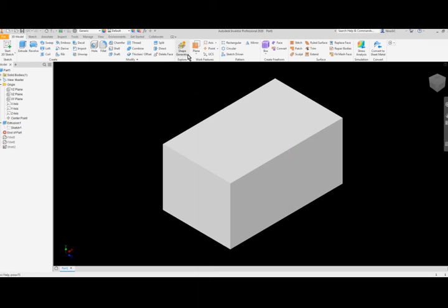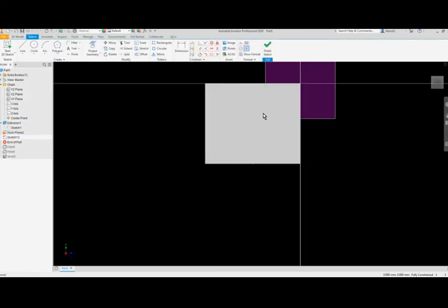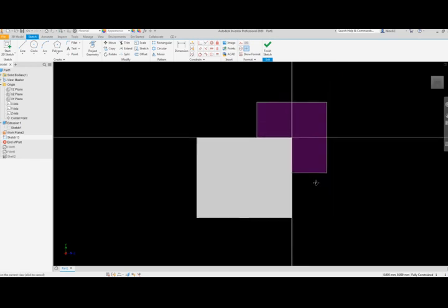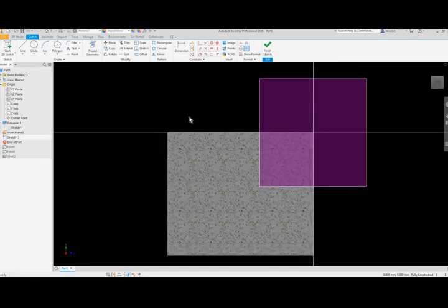If I want to create a central work plane which is not as large as the selection of the 2 planes, I can also click on plane, run my cursor on the edge that is associated with the plane that I want, left click on the midpoint, and then left click on the edge. So that produces the exact same thing. Now, what does a work plane do? It allows me to sketch. So if I select on that work plane, okay, I can hit F7 and I can see where that work plane is.